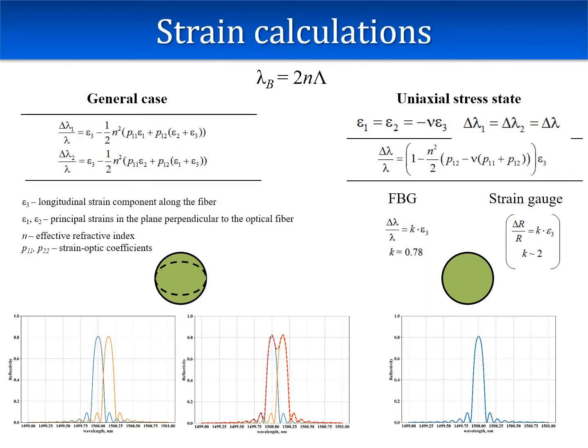One of the issues in strain measurement with the help of fiber optic sensors based on the Bragg grating is the calculation of the strain based on information from the sensor and its correspondence to the material strain. The known relation establishes the link between the physical quantities recorded by the sensor and the strain in the zone of the optical fiber with the Bragg grating. These relations have a unique solution under the condition of a uniaxial stress state in the optical fiber. However, in the general case, for an optical fiber embedded into material, a complex stress state is realized.